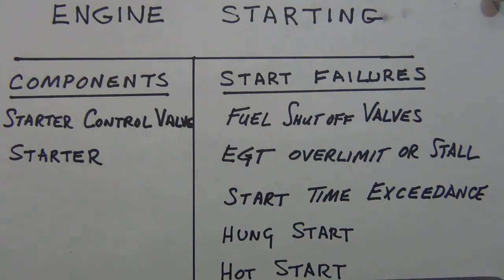Now, an external engine fire. The warnings below here I'm going to share with you are going to be showing on display when there's an external engine fire. There's the overhead one warning display, and there the engine fire push button will illuminate. You're going to have a repetitive chime that sounds, and your master warning lights are going to be on.